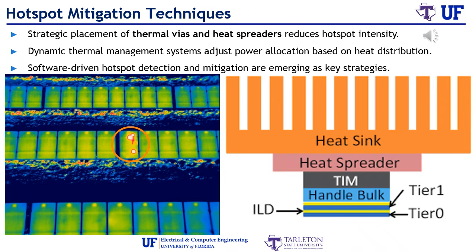On the architecture and software side, on-die thermal sensors track critical points in real time. When a hotspot forms, the system can respond with dynamic frequency scaling, voltage adjustment, power gating, or workload migration. In multi-core processors, tasks can be moved away from a heating core. This combination of static layout choices and dynamic runtime control lets chips push performance close to physical limits without crossing unsafe temperature thresholds.